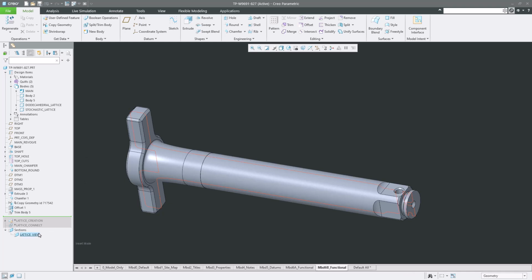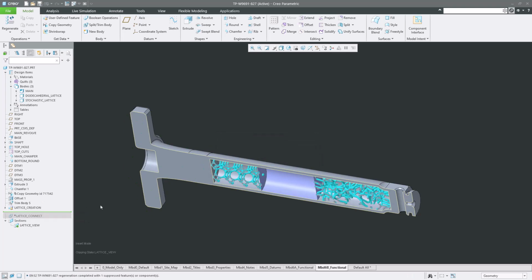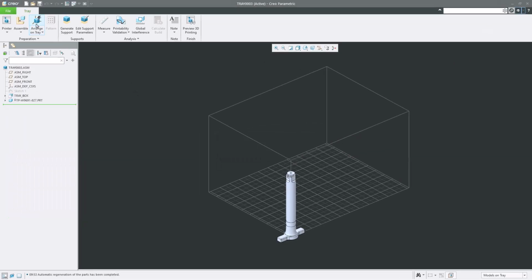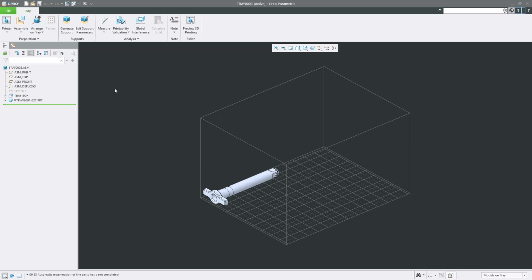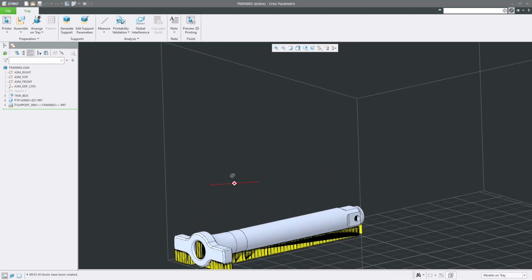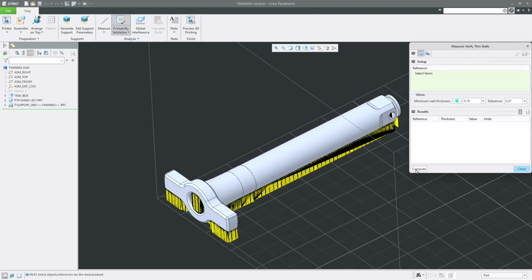Next, let's jump into Creo's manufacturing capabilities, starting with additive. You can create structures like lattices in Creo, allowing you to create sturdier, more complex parts for additive manufacturing. Creo also has a 3D printing tool built into it, where the user can prep their model for printing. You can add multiple models for the same tray, and perform tasks like generating support material, running calculations that validate things like wall thickness and hole size, and preparing and slicing the model for 3D printing, all without leaving Creo.